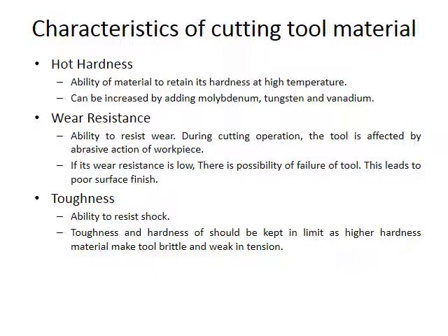The second point is that it can be increased by adding molybdenum, tungsten and vanadium. By mixing in a higher molybdenum percentage, tungsten percentage or vanadium percentage, you will definitely get the ability of the material to retain hardness at high temperature.